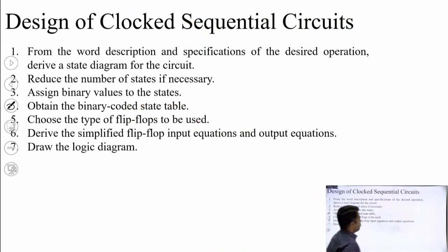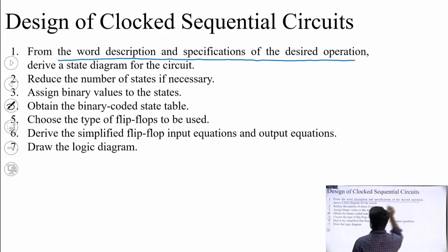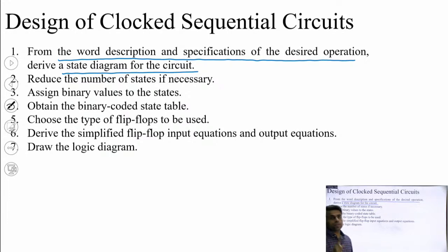In designing, the first step is, from the word description and specification of the desired operation, derive a state diagram. In the analysis part, the state diagram was the last step, but in the design process, the state diagram is the first step.